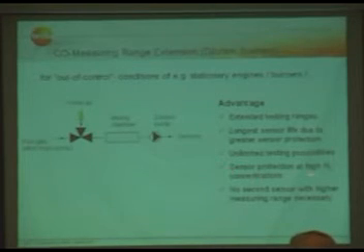The CO sensor is cross sensitive to H2, and H2 will be created if you have very little oxygen and very high CO readings, that means when lambda is less than 1. At these conditions, especially at a gas engine, you can have very high H2 readings, and this can influence the accuracy of the CO reading. That means the cross sensitivity of H2 to the CO sensor is 60%.